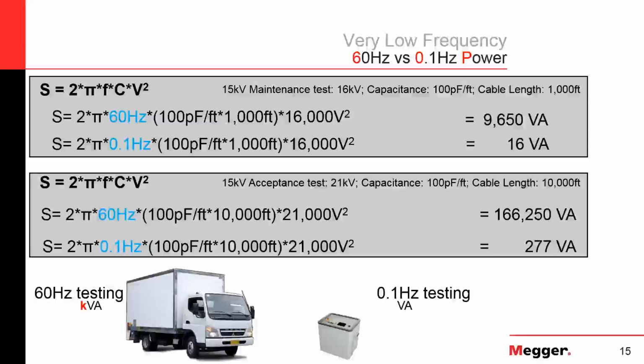And if we take this 15 kV class cable, do a maintenance test on it, cable's 1,000 feet long, we would need just under 10,000 watts of power just to charge a cable up if we do it at 60 hertz. But if we do the test at VLF frequency, it takes less than 20 watts. So maybe I can go down to the local hardware store and buy a 10 kilowatt generator, but it's probably the biggest one they have on site. And that doesn't take into account any losses or anything. And again, this is only a 1,000-foot cable.